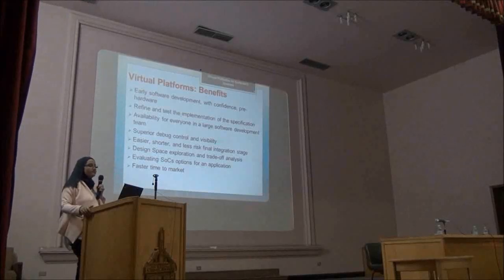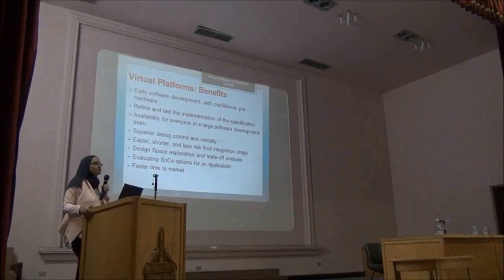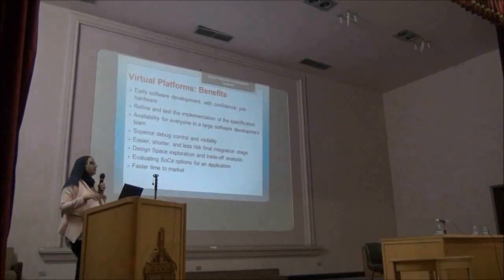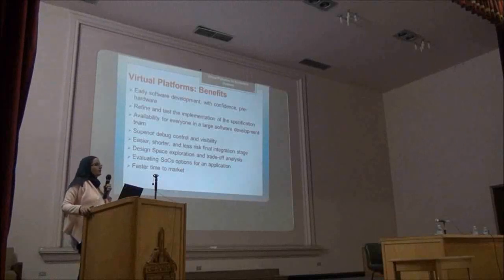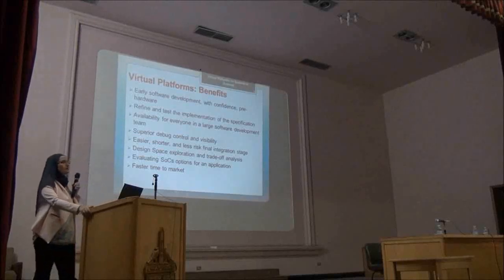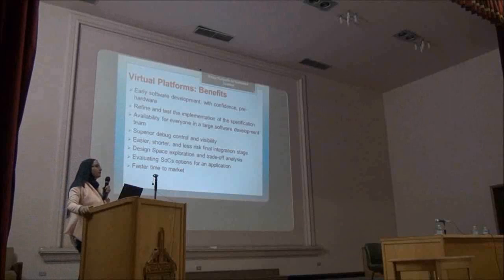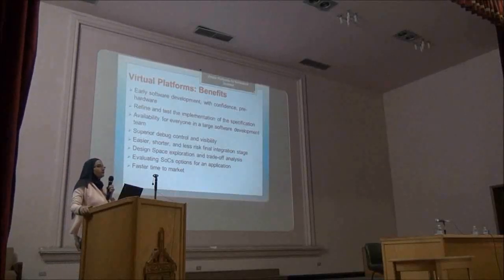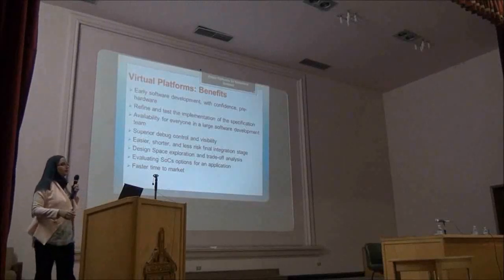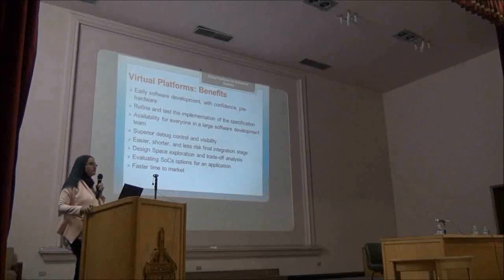It can also help in design space exploration and trade-off analysis. What if you still didn't determine how many cores are needed, whether you need a DMA, direct memory access controller, with 2 channels or 8 channels, or whether you need more CAN controllers, or one CAN controller is enough? So you can explore this easily using a virtual platform and determine what is best for your target application.